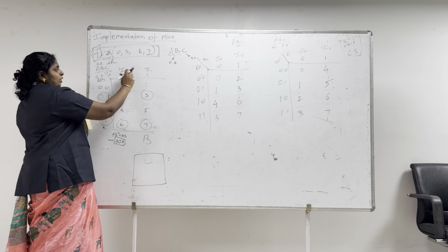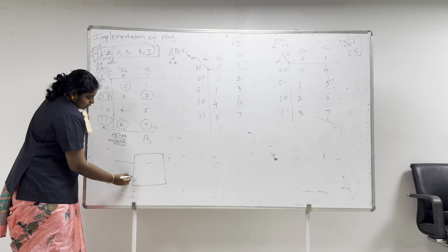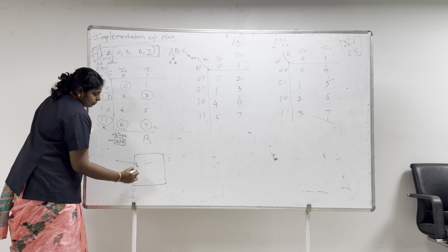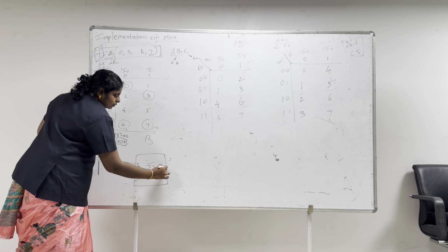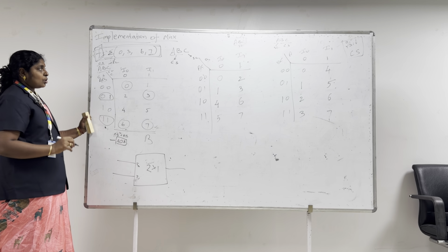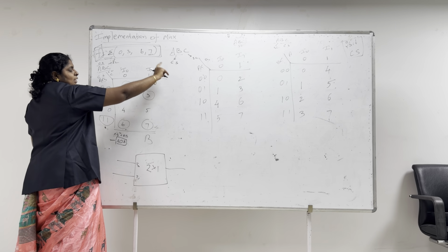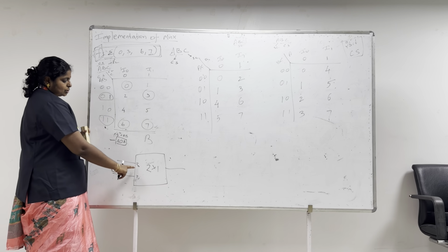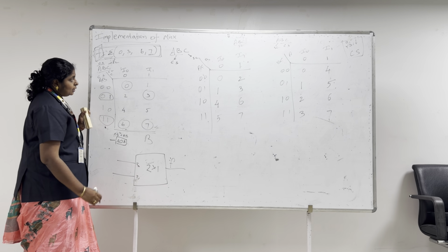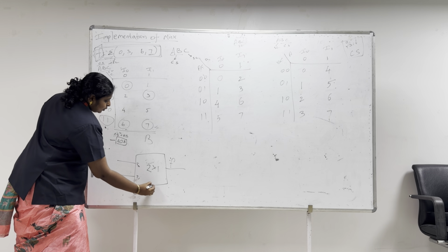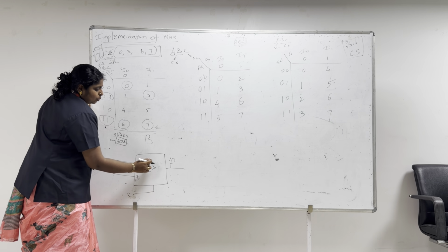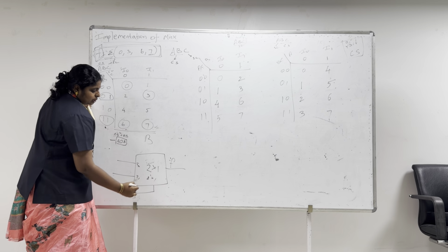So over here, there are only two inputs, I naught and I1. Therefore, what will be my configuration? Only two inputs, so 2 cross 1, right? When you take 1 as a control signal, the configuration is 4 cross 1, but over here with 2 as control signals, my configuration is 2 cross 1. So I naught and I1, my output is F. Now, what is my select line? Only C. Only 1, 2 power 1 cross 1. So my select line is 1.